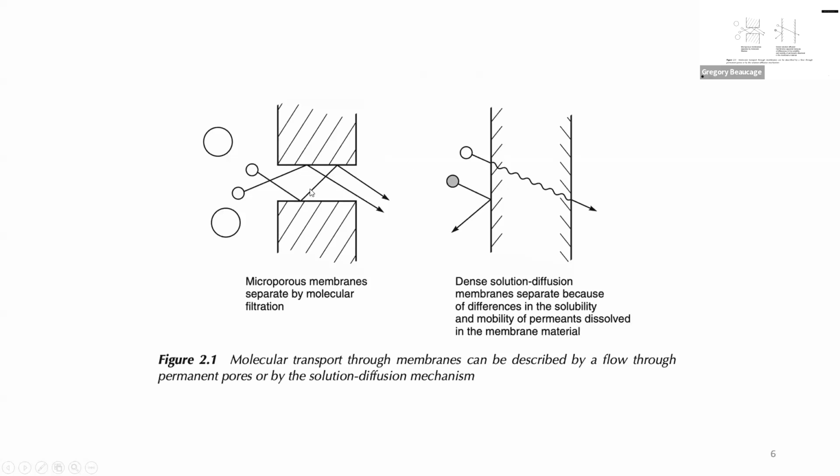This is the separation concept. There's an issue of what happens in this tunnel. If the particles are hitting each other, that's Brownian diffusion. If the particles are doing what they show here, that's Knudsen transport, right? Which is slower than the particles hitting each other. If you're measuring pore sizes and trying to find a dependence on pore size with the transport through it, you'll find there's a transition point where you go from continuum to this kind of molecular scale transport.